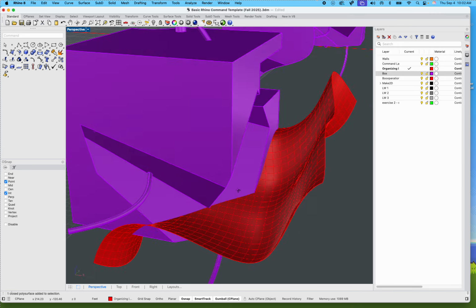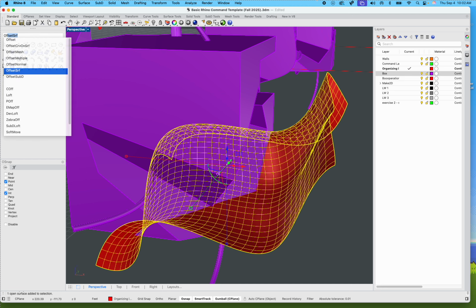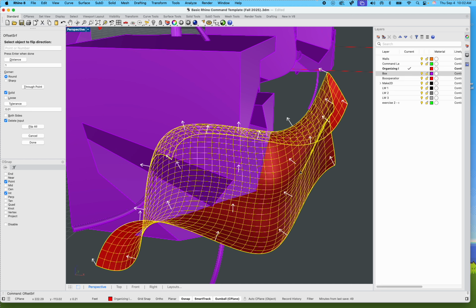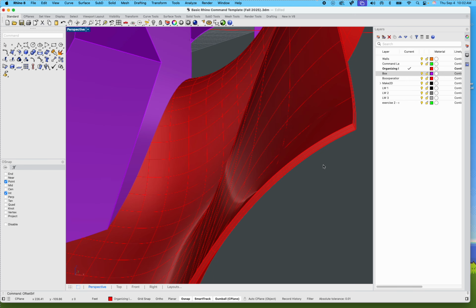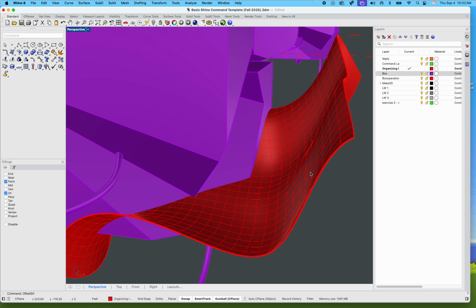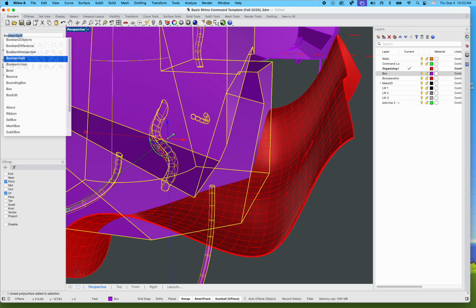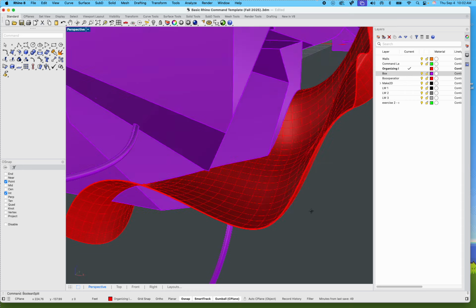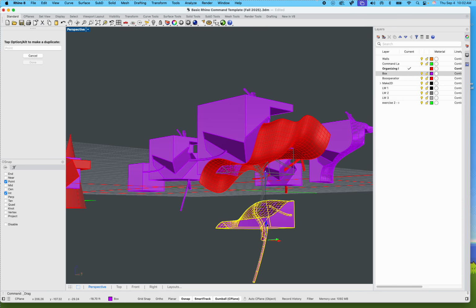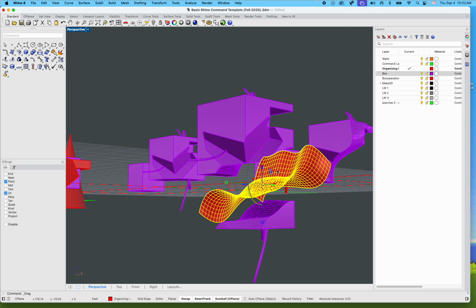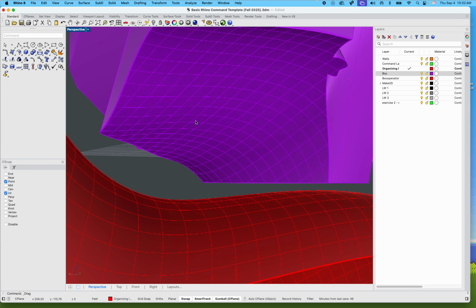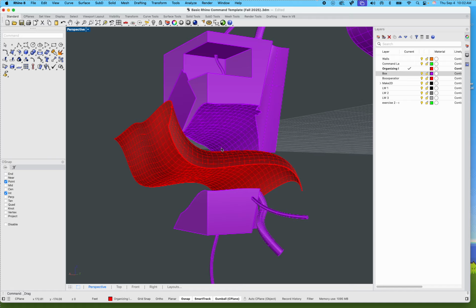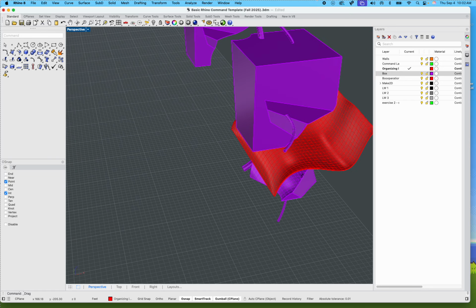But in our case, if it is not working, I can offset surface. I can give it some thickness. So in my case, I'm going to make it extremely thin, like 1 inch. And it's going to barely be noticeable. But now it's technically an object, so what I could do is Boolean difference or Boolean subtract it. So I'm going to type in boo, I'm going to type in Boolean split. Click, click, enter. And voila, it's still going to technically do the same thing, right? But arguably now I have all three, and it nicely enough keeps the surface, so that's kind of a plus. So anyway, just wanted to make sure that you guys are in the right spot when you're going over this part.